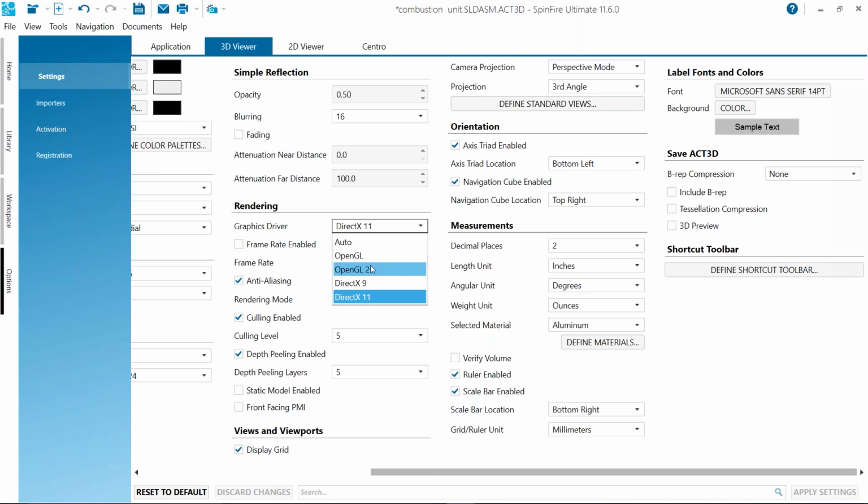I've seen them where they're 5-6 years old. The technology here is new. It requires newer software sometimes. But probably the first thing I do is check your graphics drivers, the dates on them, and come under this rendering section and just drop it down one at a time and apply it, close and restart. See if that helps. Yeah, that would be the first few things I would think of.